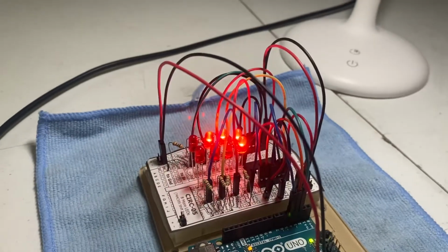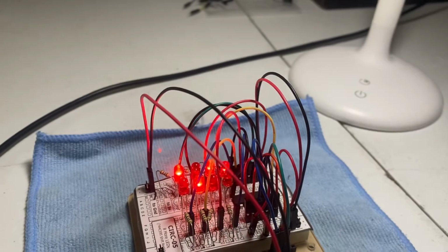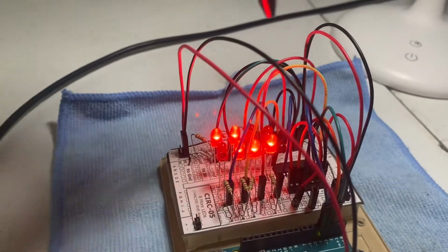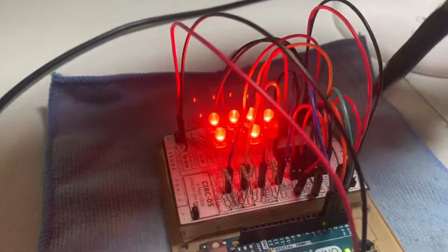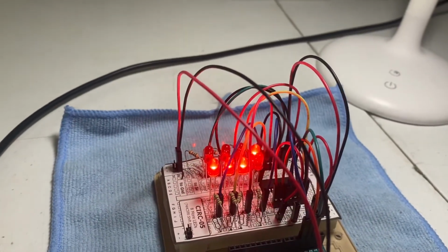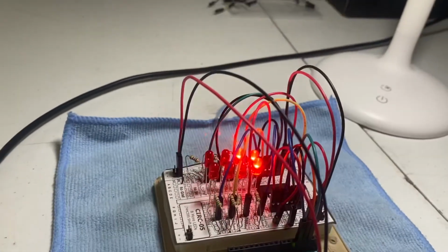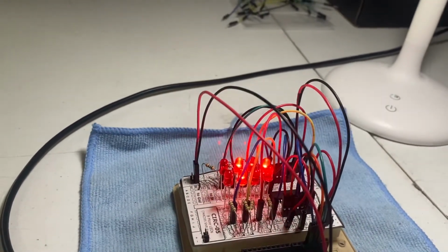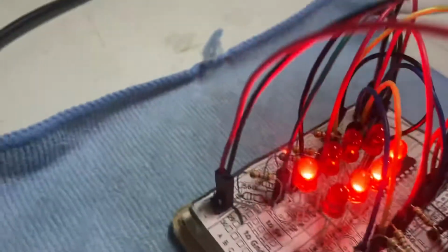Using the shift register, we only have 3 data pins on the Arduino that connect all LEDs to the shift register through individual wires. We have these 3 that are connected to the shift register, and then each LED has its individual wire that's connected to that chip on the breadboard. All of these components are powered using the same 5-volt and ground pins on the Arduino, these 2 right here, and on the Arduino by using jumper cables accordingly, and all 8 LEDs have the respective ohm resistors to prevent burnout. Each one has its own ohm resistor.